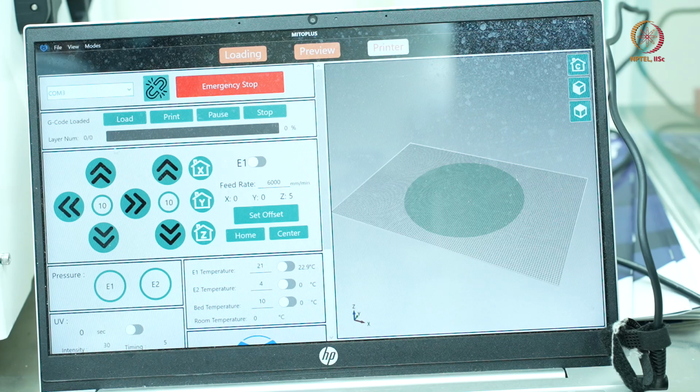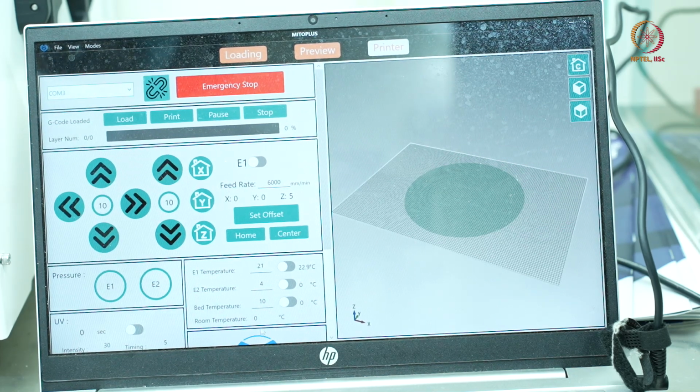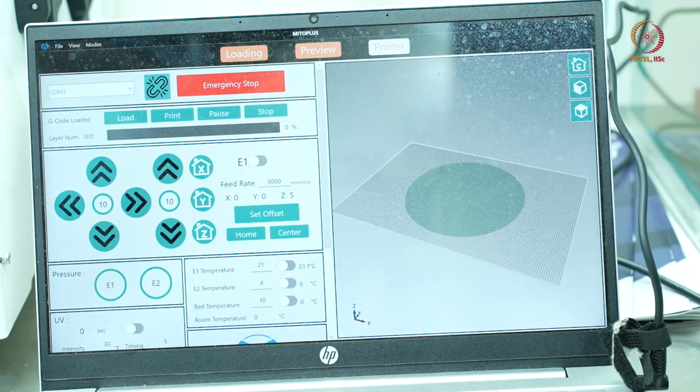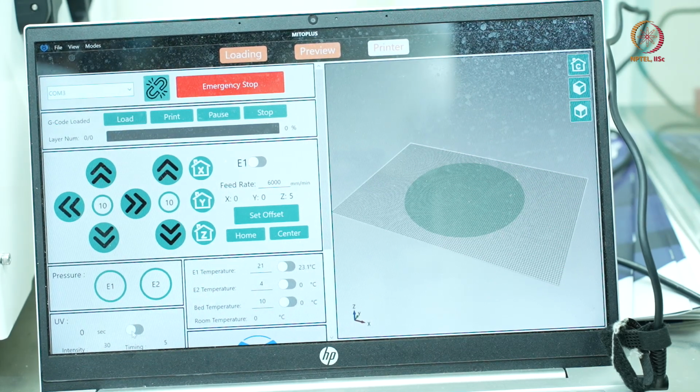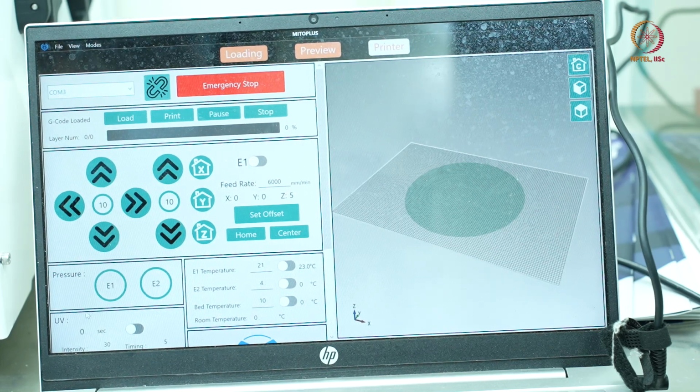So this is again the extrusion head. You have print heads 1 and 2, and then one has to set the temperature and bed temperature before anybody can start the printing operations. Another thing you notice is that in the bottom left panel, there is the UV window. There are a couple of unique numbers: you can select UV on for 5 seconds, 4 seconds or 3 seconds, and set the intensity and the timing. So if you want to do in situ UV cross-linking operations, it is possible.